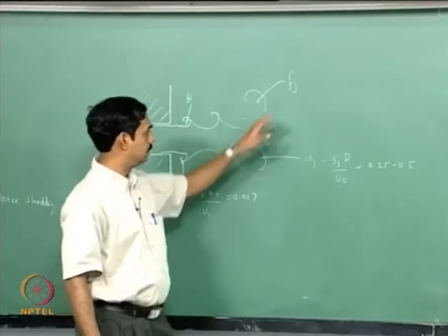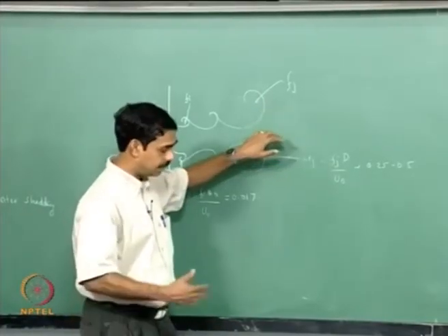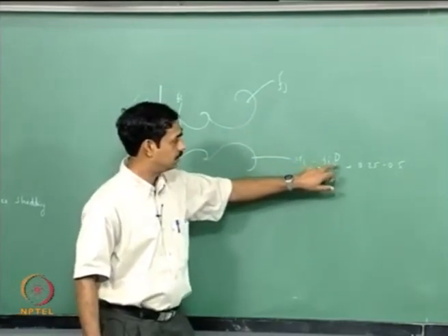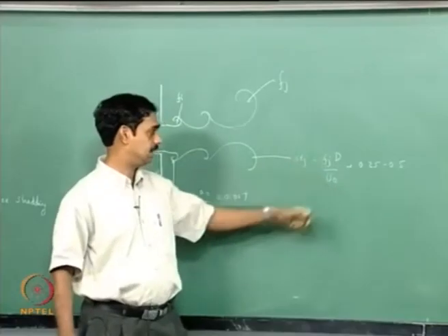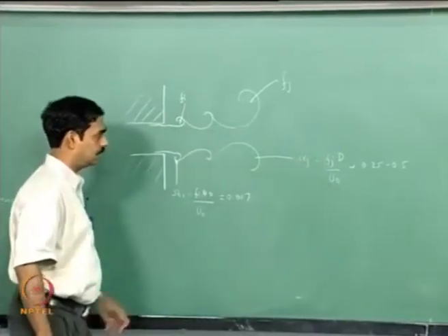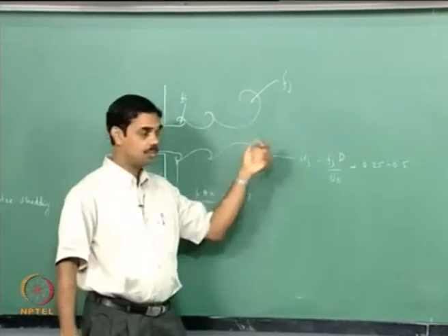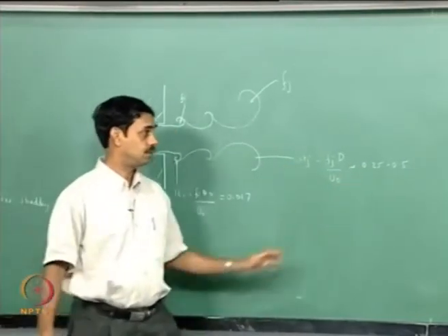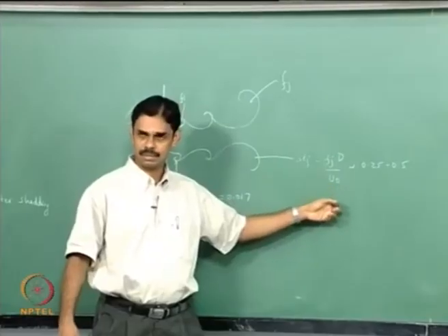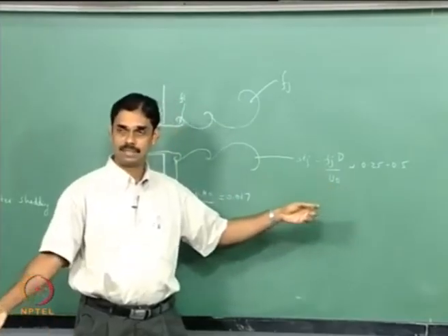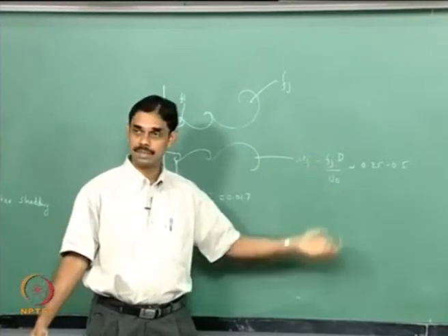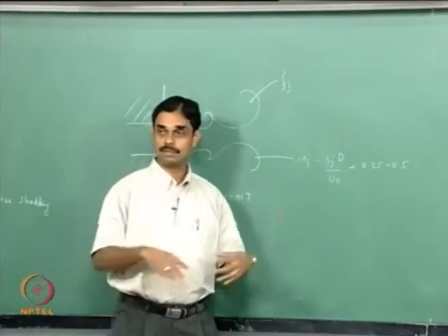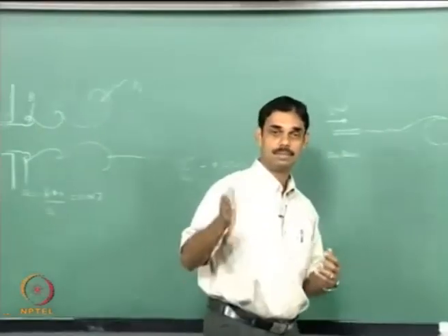St_J, that is, at the jet exit or at the end of the jet core you have a Strouhal number scaling in terms of the diameter of the jet and the jet exit velocity. This frequency would usually be lower, and its Strouhal number is of the order of 0.25 to 0.5. So this frequency would be called the preferred frequency of the jet. If you excite at these frequencies, then you will get a very large response of the jet, and this vortex will become much more coherent and the spectra will become more sharp.